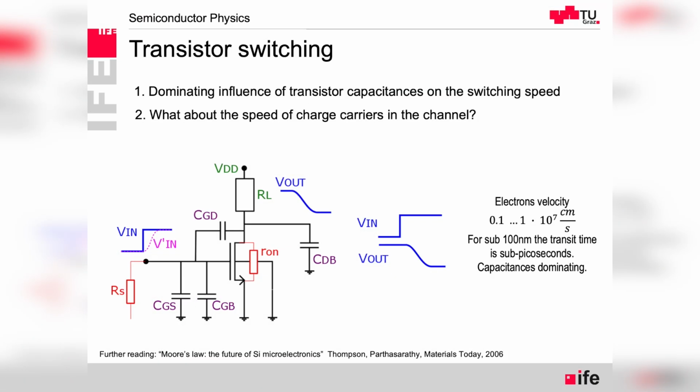As an example where this capacitance might be important, let's consider such an amplifier circuit where we care about high transconductance, so that a small signal at the input will translate to high currents through the drain, and the output will also be large. With the gate-source and gate-bulk capacitances, the V-in is at the bottom of the source resistance.